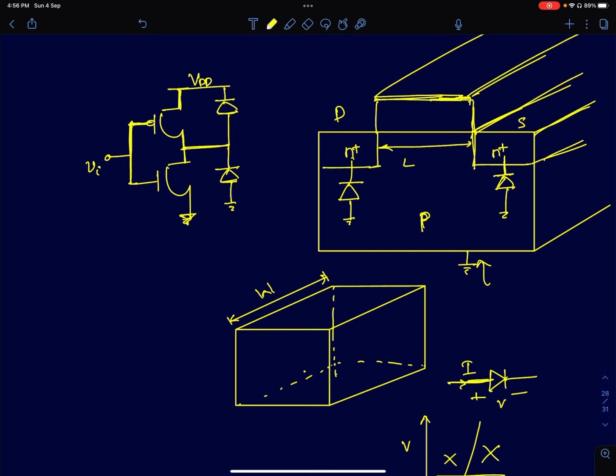But at that time, there was a very promising solution which used a technique called open loop modulation. You have an oscillator, and generally we need a PLL to set its frequency. But the PLL was a power consuming block, and Bluetooth means it's a very low power system. So you'd want the oscillator to operate in open loop.